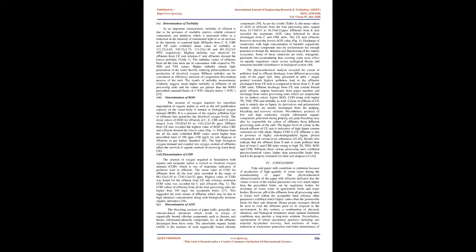It is obvious that TDS values in discharge from all the processing units are higher than the WHO maximum permissible limit of 500 ppm, 500 mg/L, for the disposal of wastewater into surface water. 33. Increased concentrations of dissolved solids can also have technical effects. Discharge of wastewater with higher TDS in water bodies may increase salinity of water, thereby making it unfit for irrigation and drinking purposes. Consumption of water with high TDS is reported to cause detrimental impact on alimentary canal, respiratory system, nervous system, coronary system, besides causing miscarriage and cancer.